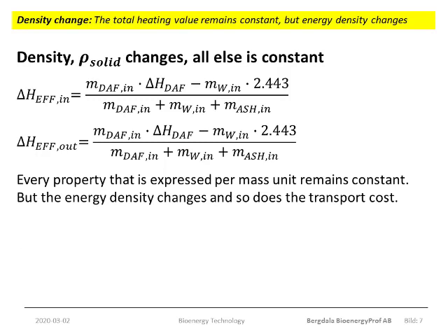Compaction, like pelletization, changes nothing except the density. So all chemical properties of the fuel remain constant. The same thing goes for grinding to a fine powder aimed for pulverized fuel firing. Pelletization will increase the bulk density, while milling will decrease the bulk density.